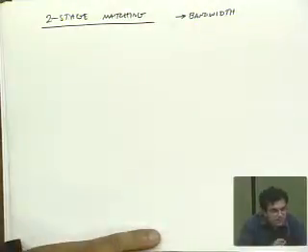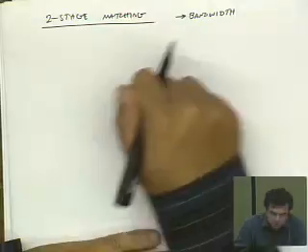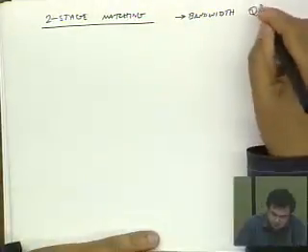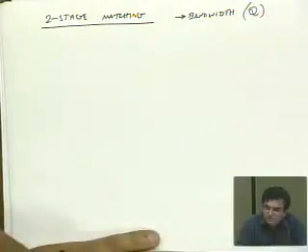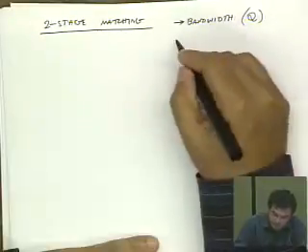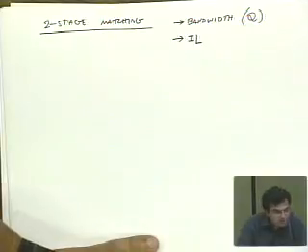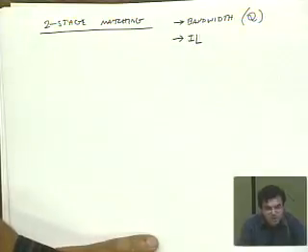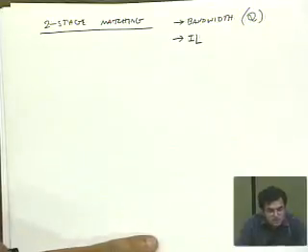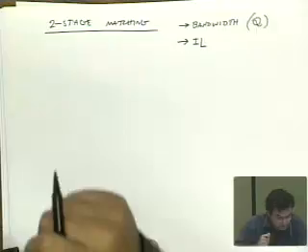Another degree of freedom for what? To design the Q, for example. Okay, but that's bandwidth, right? Yeah. Okay, anything else? Well, how about insertion loss? Is it possible that by using more stages we can get less insertion loss? In fact, it's true, you can. And the reason is that insertion loss is really related to the network quality factor. And in certain circuits that you have extremely high network quality factors, using multiple stages can actually relax the quality factor. We'll see how that works out in a moment.